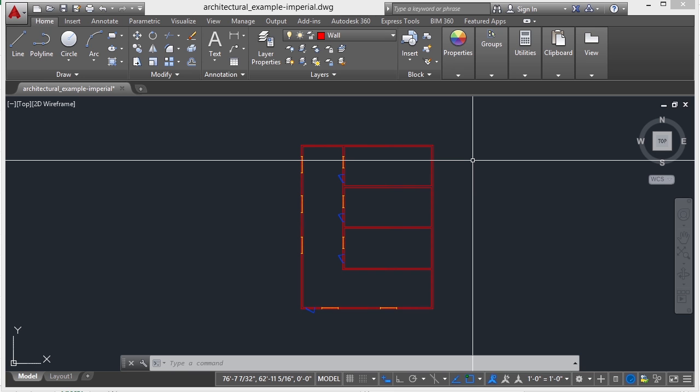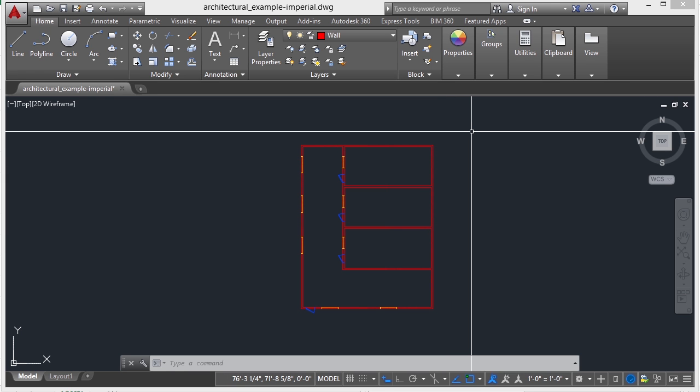By creating layers, you can associate similar types of objects by assigning them to the same layer, as was done in this example. With layers, you can then control the following. You can control whether objects on a layer are visible in any viewport. You can control whether and how objects are printed. You can control what color is assigned to all of the objects on a layer. You can control what default line type and line weight are assigned to all of the objects on that layer. You can also control whether objects on a layer can be modified. You can lock down your line work that way. You can also control whether objects display with different layer properties in individual layout viewports.